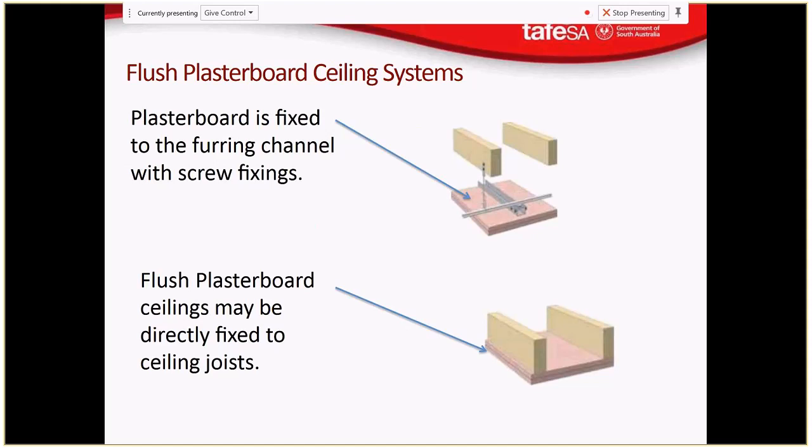How do you screw the hook to the concrete? That would be with a masonry anchor, yeah. The different types of ceiling system manufacturers will specify their masonry anchors for that. Look, I don't know specifically. I imagine you'd probably want to fix them with a shock-fired masonry anchor for speed of construction, because you've got a lot of these hangers to install. But yeah, the specifics of that, I'm not sure.